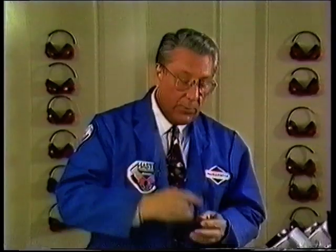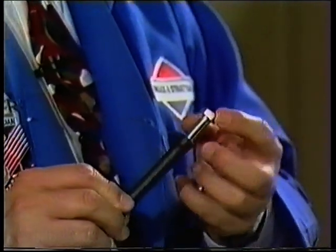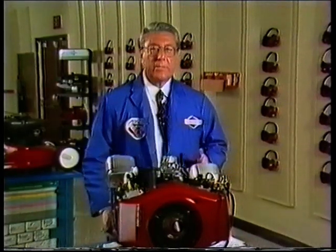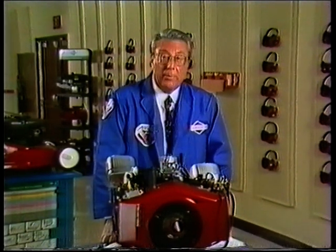So, whenever you remove a fuel filter while repairing a leaky carburetor, replace it, but also replace the fuel line. And never use a bolt or threaded object to plug a fuel line during repair. The threads will cut the rubber hose and make the debris problem worse. By following the procedures we've demonstrated here, you'll save both time and money by increasing the number of repairs you complete successfully the first time.